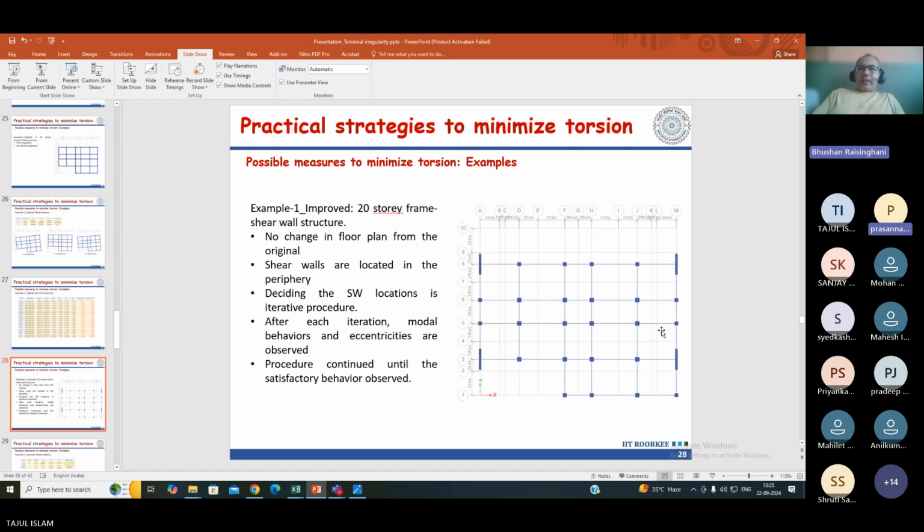How much you can practically avoid and how much is technically required, you first have to do your groundwork on that. I would suggest you do a few trials on your own building. That will help you decide better when to remodel and when not to. As it depends on eccentricity, there will be some limiting value acceptable up to this eccentricity. If you have an offset within it, you can ignore it. If eccentricity is more than that, you should not ignore it. You will come to know only when you do some trials with some models. There is model to model variation, simple model, complex model. What is the arrangement that you have? All those things are critical in this.